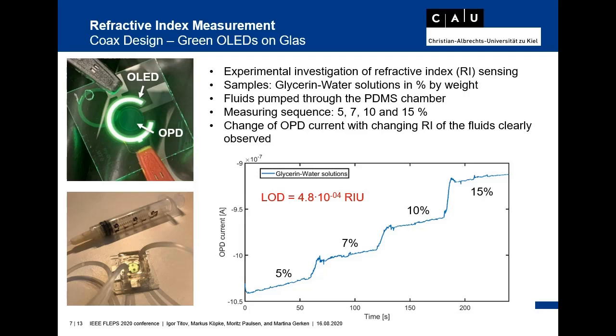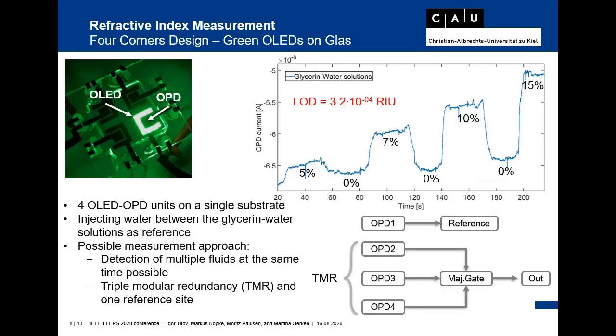And as a conclusion, the increase of the refractive index of the fluid was clearly observed, but we also see a degrading effect of the OLED. And this is a well-known effect actually, and can be accelerated by poor encapsulation of the organic stack due to water and oxygen impact. Further, we fabricated 4 OLED-OPD units on one single substrate.